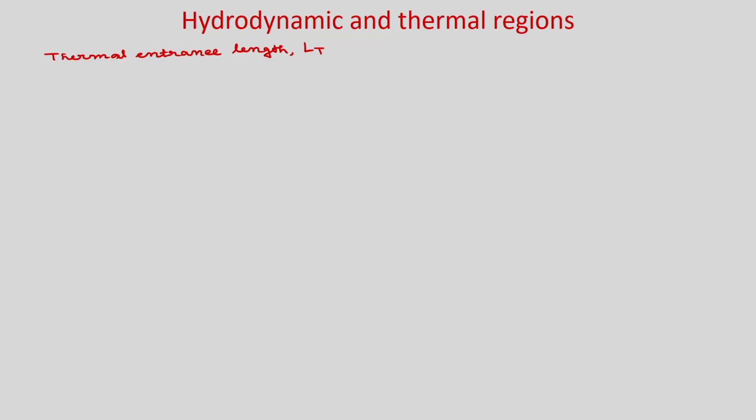Okay. So, in this particular case we will consider that velocity u is order of u infinity, or u average. So, the velocity will take the scale of u average, irrespective of the low Prandtl number fluids or high Prandtl number fluids, because both will merge ultimately at the central region.